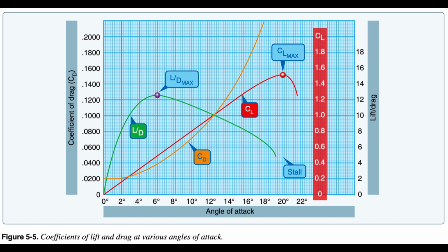Since an airfoil always stalls at the same AOA, if increasing weight, lift must also be increased. The only method of increasing lift is by increasing velocity if the AOA is held constant just short of the critical, or stalling, AOA, assuming no flaps or other high lift devices.